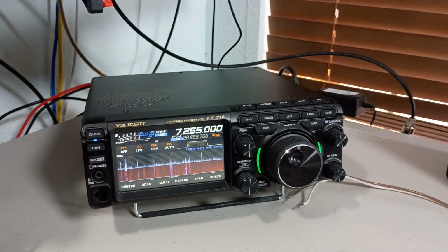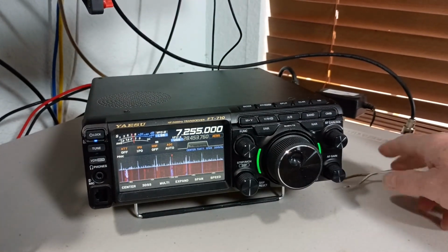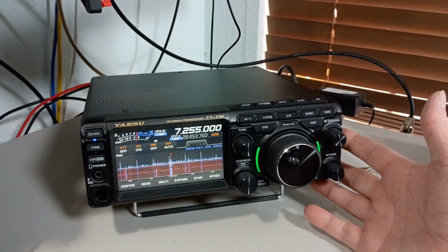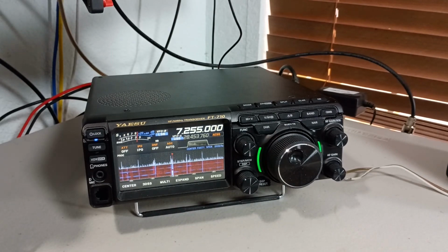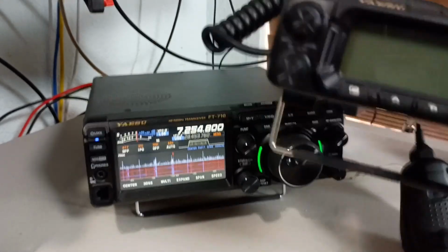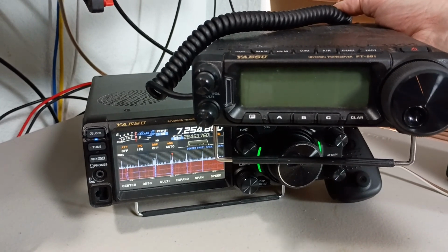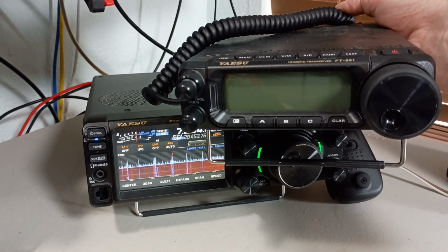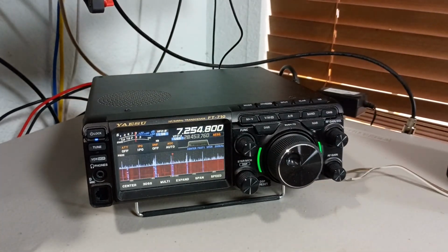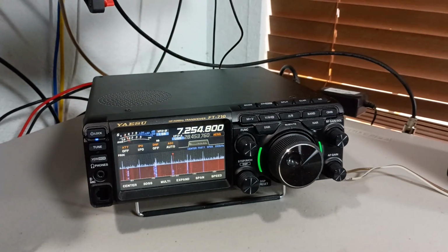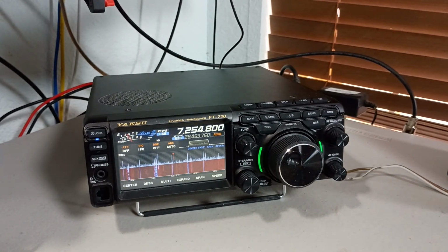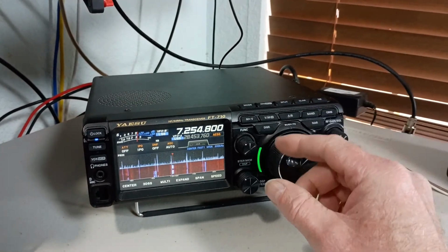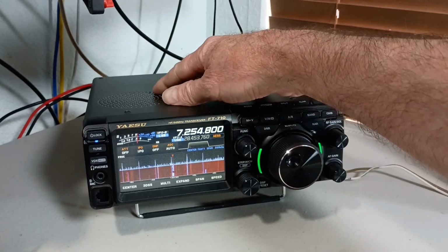the external speaker in, it activates the low-pass filter in the radio. So normally when you have a radio, for instance my FT891, when you plug in an external speaker, it disables the internal speaker and all the audio goes through the external. But with AESS, that's not the case. With AESS, when you plug in the external speaker, there's a switch in the jack, and that switch just enables the low-pass filter in the internal speaker.